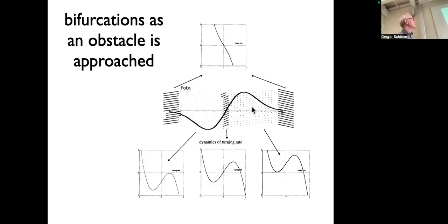So if this is the force let, there's an obstacle right here in the middle. Then I can say there are 4 regimes here. There is the center regime where I'm flying right there and I'm switching from no obstacle, attractor, to repeller. In this regime it would be symmetrical. And if I'm in this regime or in that regime, then I'm also doing that switch to a repeller, but I bias it in this way or in that way. And then outside here, I have no obstacle contribution, so I'm back to that same term. So there's a negative alpha and there's no shift up or down. And that's the summary of that.